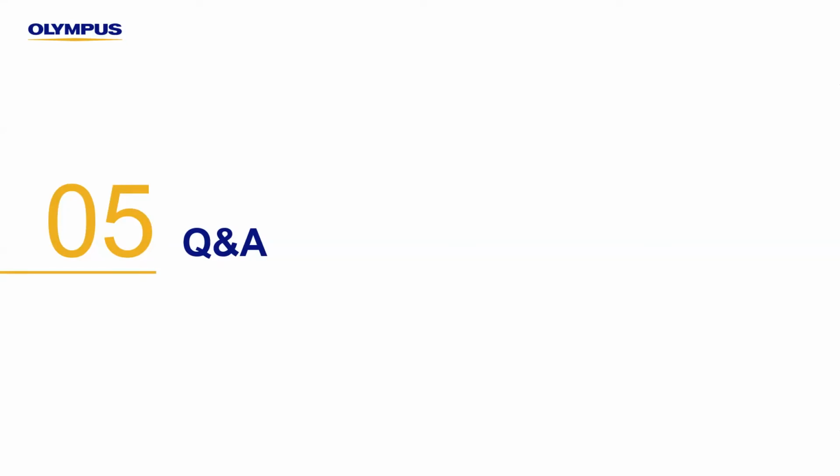How much fill factor is required? I think this is another question from India. For ECT, it's around 85 to 90% fill factor. For RFT, it will depend on the software that guides us on the fill factor. So basically for eddy current, it should be 85 to 90%.